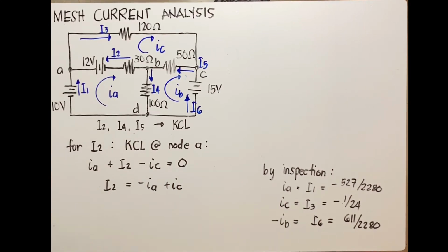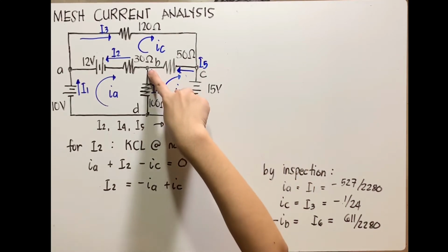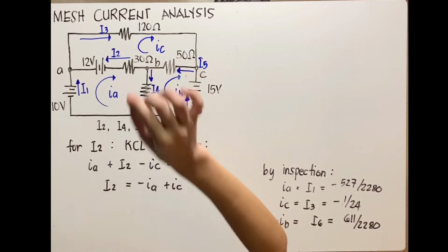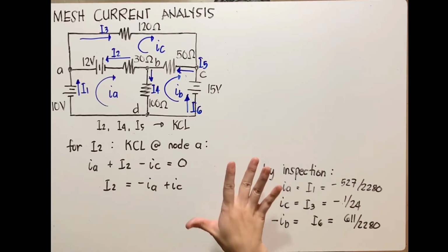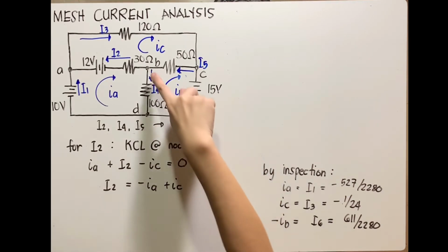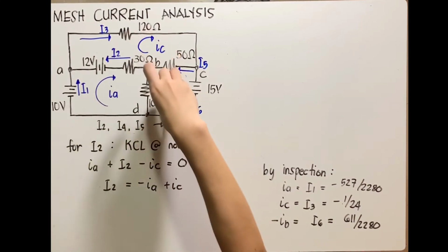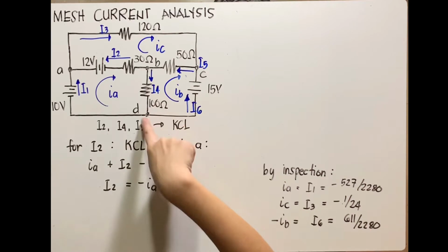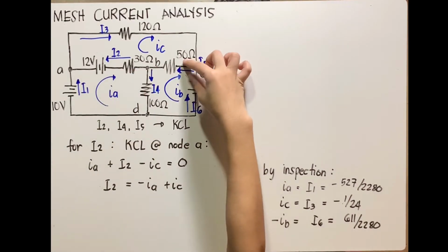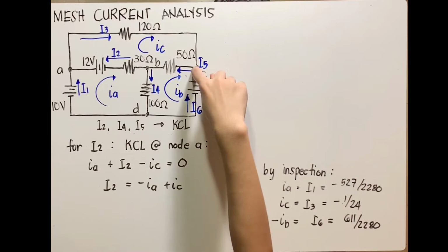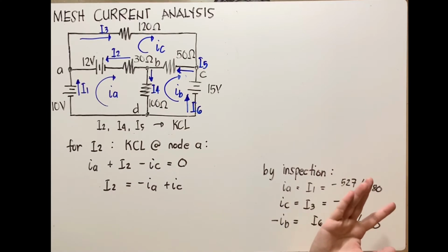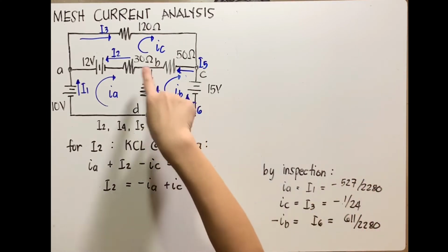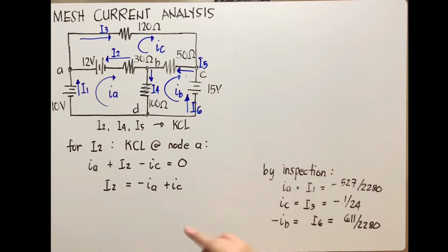Okay. No one recommends you solving for KCL at B, where B is in the middle of the three mesh currents. Okay. Pero for me, pwede po natin gawin yan. Basta tatandaan nyo lang yung sinabi ko. Kasi may mga instances para sa akin na kapag nasa gitna, yung node ng mga mesh currents, ang ginagawa nilang KCL dito, branches. At kapag branches tiningnan mo, may mga kagaya nito. Pag nag-KCL ako sa B, I have I2, I4, I5, lahat yun nawawala. So, anong ilalagay mo, di ba? Pero may mga circuits kasi na if you KCL in the middle, mas napapabilis niyo yung solution. I think I have an example for that. So, you watch out for that.